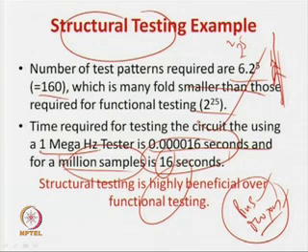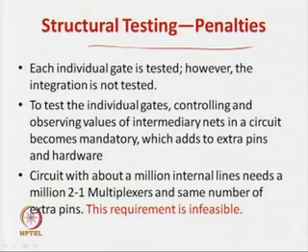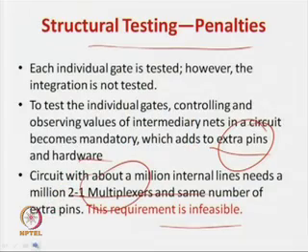So, research has been done, which we will study in this course, and we will see something in this lecture today also, on how pins and multiplexers can be brought down, which is feasible. But still, taking the test frequency higher and going for functional testing is a difficult problem. So, that is about the structural testing penalties which we have discussed. You require extra pinouts and some multiplexers, and these requirements are actually directly infeasible. So, you cannot have that high requirement. So, let us see how we can handle the problem of extra pinouts and extra multiplexers.